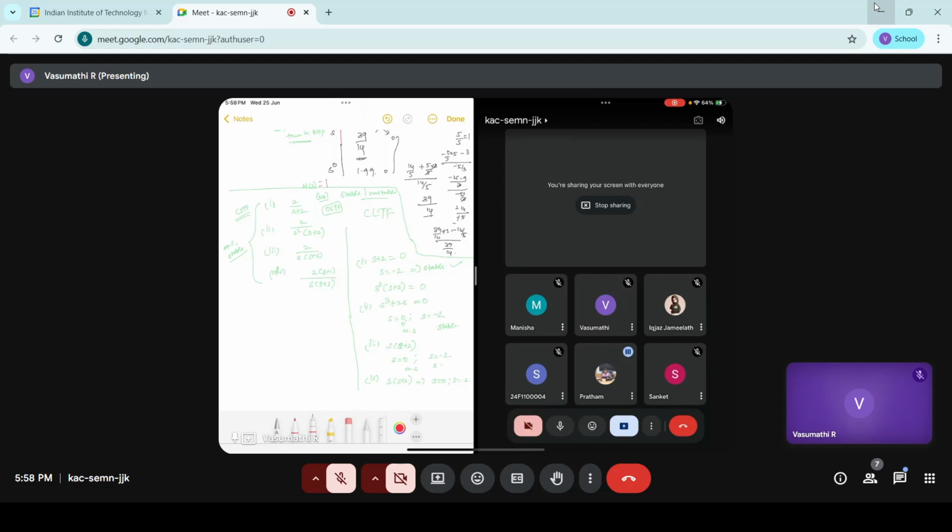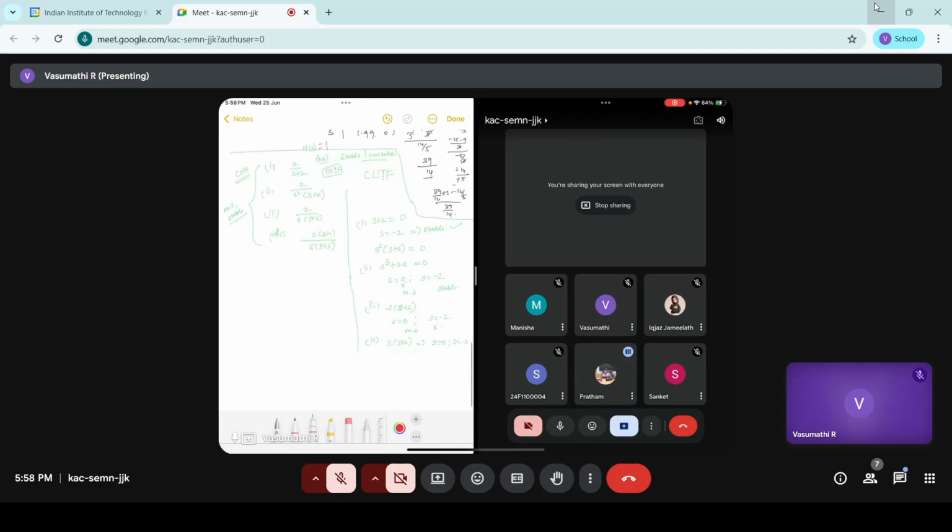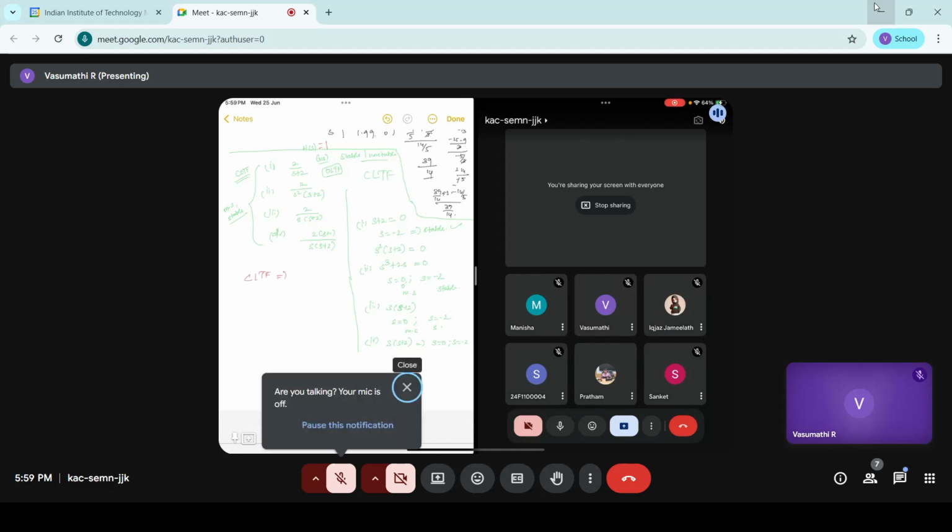So for G(s) also, it's like the previous answer, all are stable, like what you have done on the right side. No, you have to find the closed loop transfer function for all the systems. Oh, that was for open loop, no? No. All these I'm giving now, consider it as G(s), not the closed loop transfer function. For the first ones, I asked you to find the closed loop transfer function, considering it as Y by R. Now consider it as only G, and then consider H equal to 1. Find the closed loop transfer function for each of the systems.